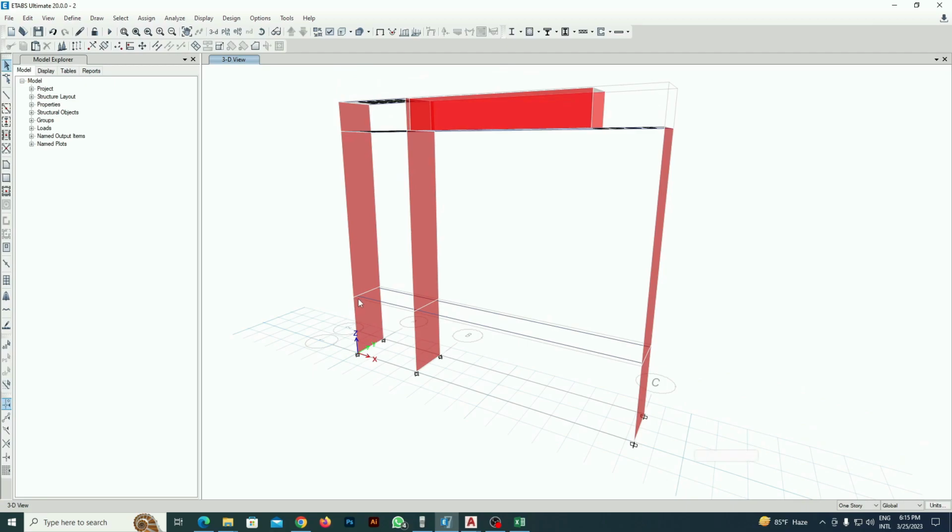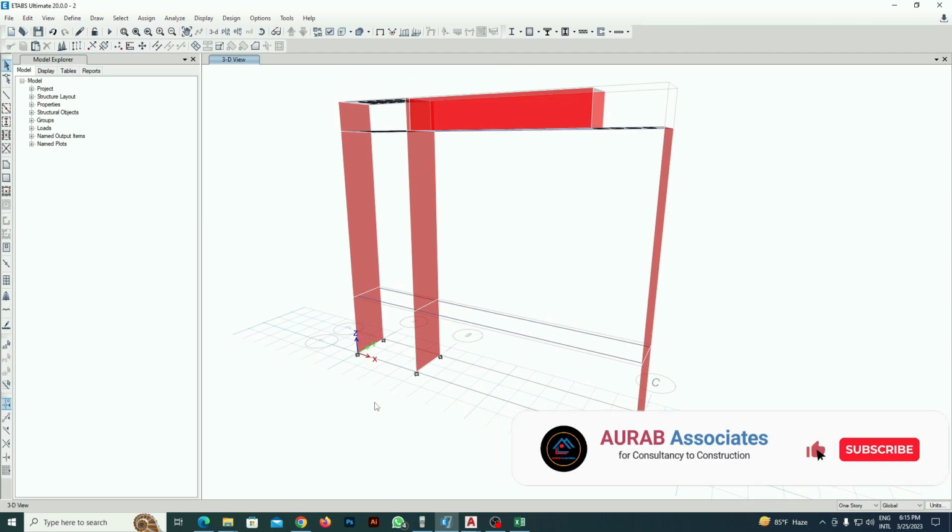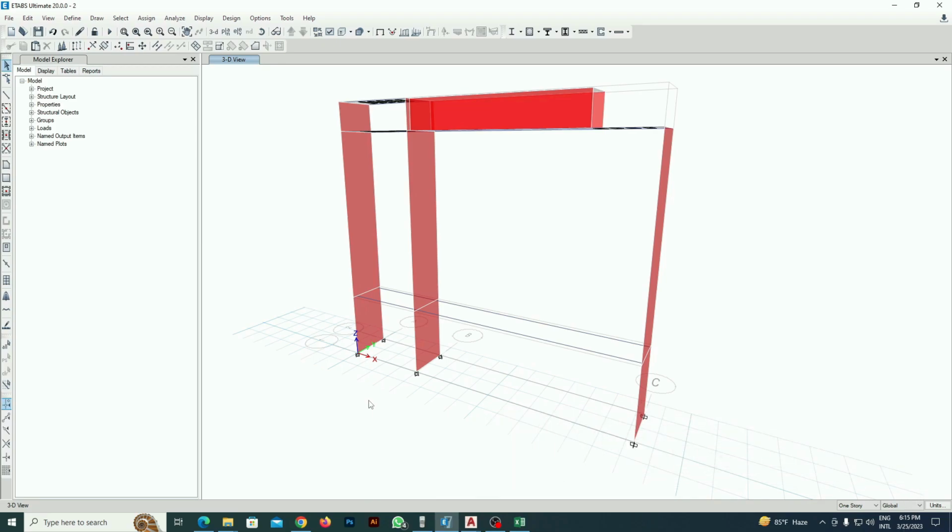I could try with some more depth of soil cutting or soil excavation. If this also fails, in that case I had to provide pile foundation. So this is the final concept. You have to increase the weight, or if it is not possible, then you can increase the height of soil excavation, or if this is also not possible, in that case you have to provide pile footing or pile foundation.